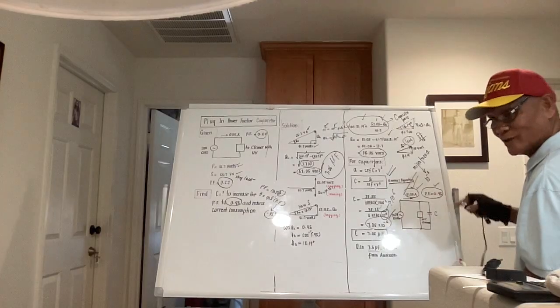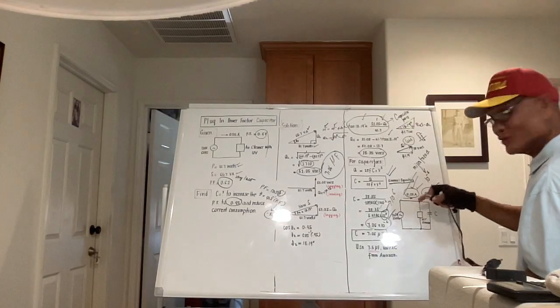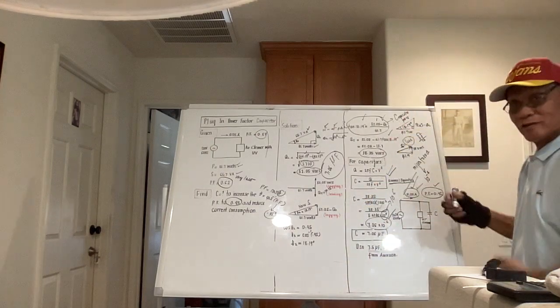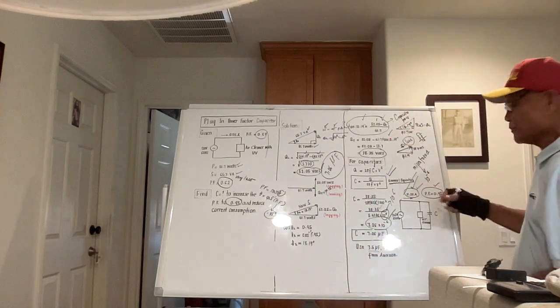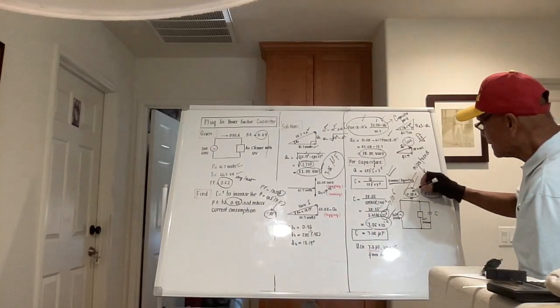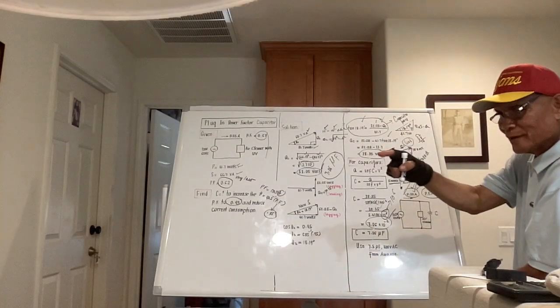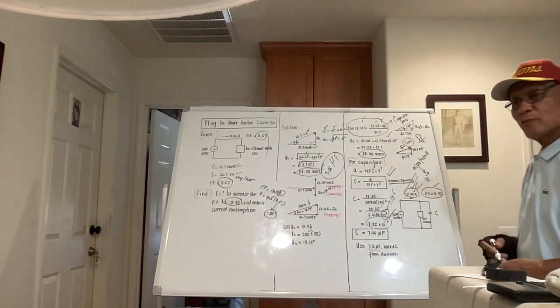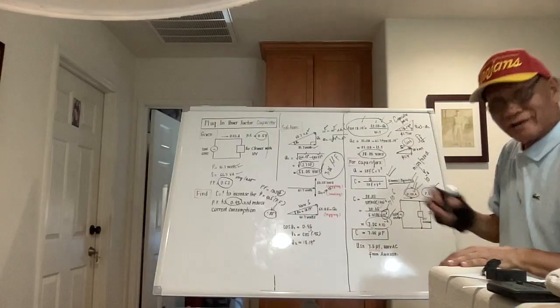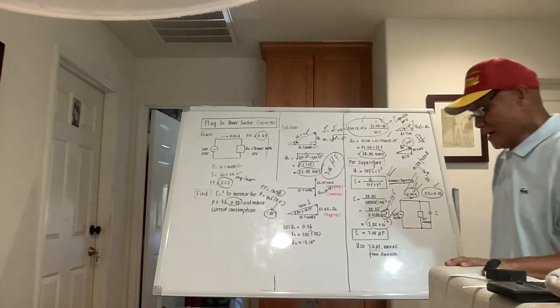They try to fight each other, so the total current drawn now will be less. If we compute the current after the addition of the power factor capacitor, it is 0.35. From 0.55 to 0.35, if we compute the percentage, it's 38% lower. Okay, that's it, guys.